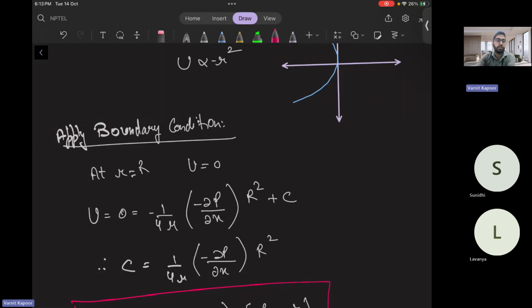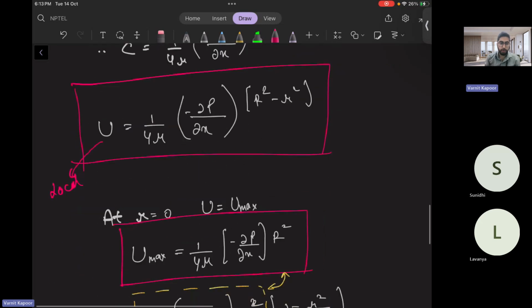Now we need to find the mean velocity. Why did we come across the mean velocity? We get the mean velocity from the discharge. Discharge will always be constant when flowing through a uniform pipe, so from the discharge balance we get the mean velocity or average velocity concept.